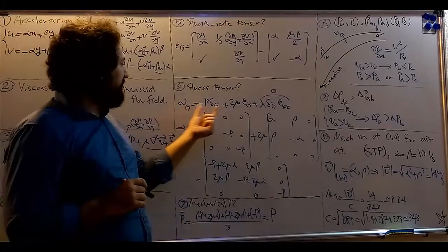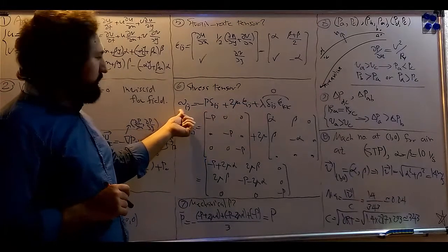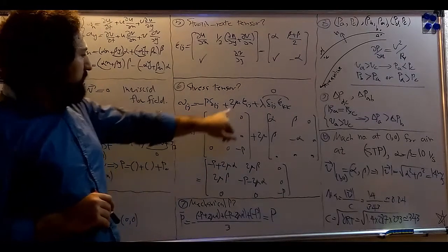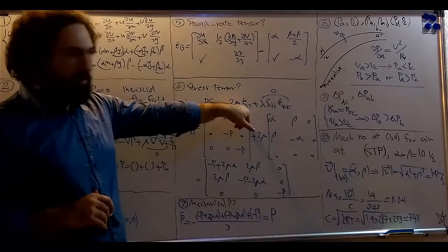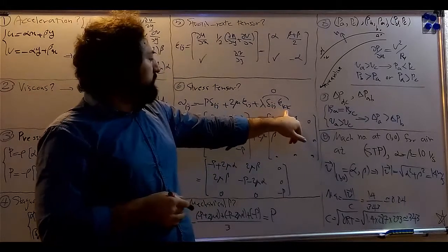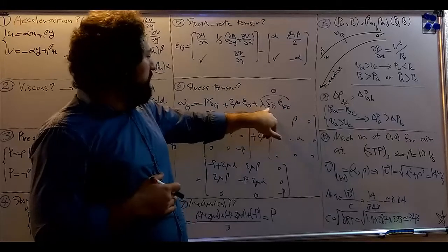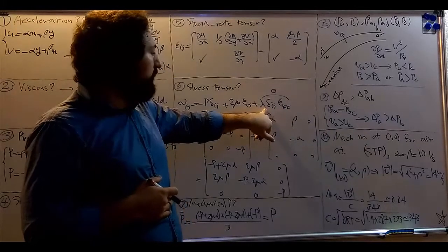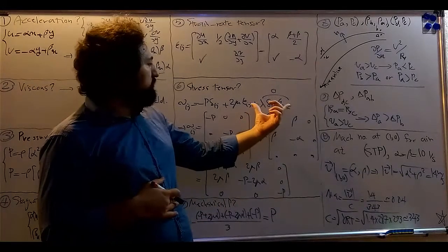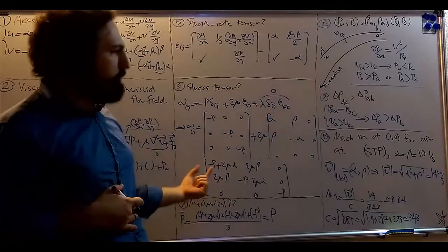This is a linear relation between the strain rate tensor and the stress tensor. This is the hydrostatic pressure. This is the Kronecker delta, the first coefficient of viscosity or the dynamic viscosity. This one is the contracted form of the strain rate tensor, which equals the divergence of the velocity field. The second coefficient of viscosity, or the bulk viscosity, and again the Kronecker delta. The last term in the relation is 0 because the velocity field is incompressible and its divergence is 0.